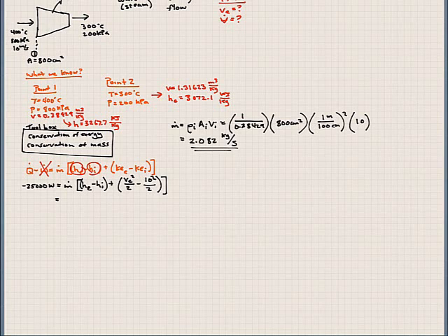And remember, this is a steady operating system, so the mass flow rate, and there's no other inputs in our nozzle, so we don't have anything else coming in. So our mass flow rate is constant, or it's conserved. So what's coming in is coming out. That'd be the same value at the exit. So regardless of where we take it, the mass flow rate is the same at inlet or exit.